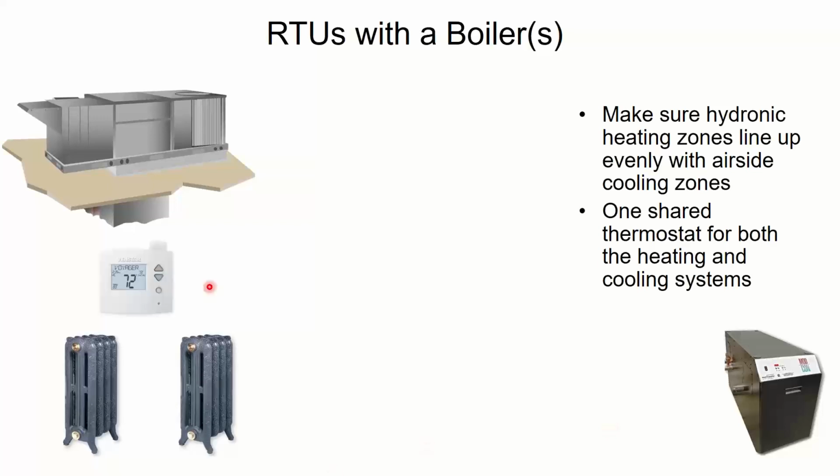Now you may have more than one thermostat in there, that's fine, or more than one radiator in there, but I'd like to have one single thermostat turn my cooling on and open the valves to both of my radiators, or all 10 of my radiators, or however many I have in this case. One thermostat controlling both. If you have two thermostats, the problem ends up happening that, well, if somebody makes this one call for cooling and makes the other stat call for heating, now I have heating and cooling running at the same time, which is a massive energy waster. So one thermostat controlling both is the way to go.